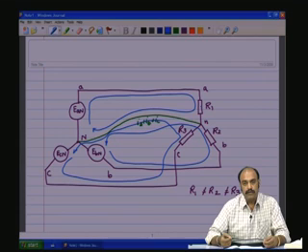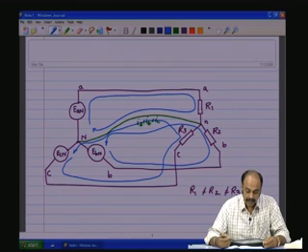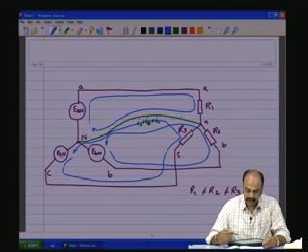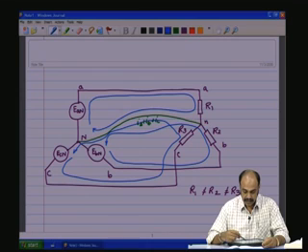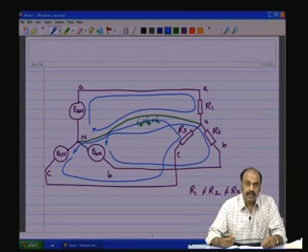The voltages across all the three phases will still be the same as decided by the source, whereas if this green line, the neutral connection, is not there, then the unbalanced currents will get mixed up and flow through the other loads, and then you can have voltage distortions.